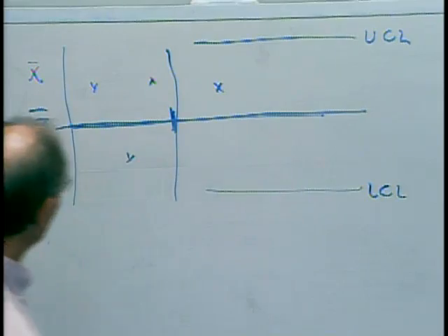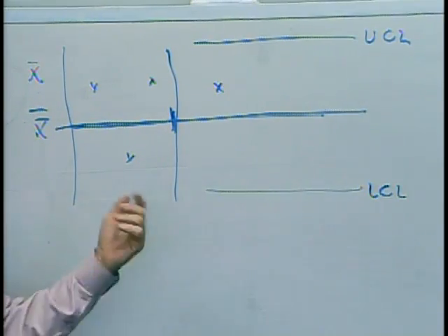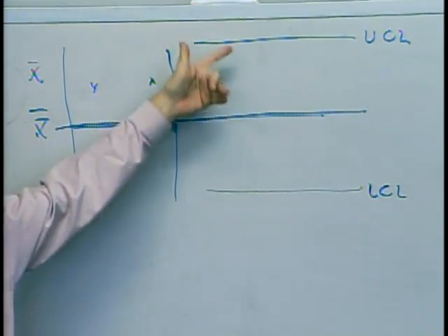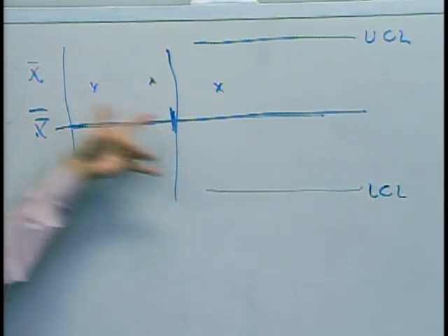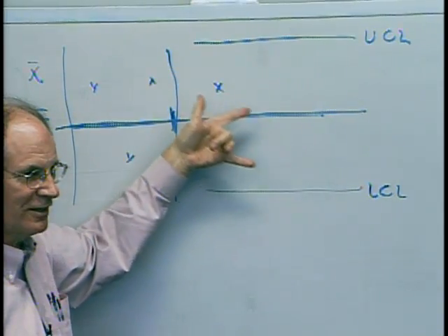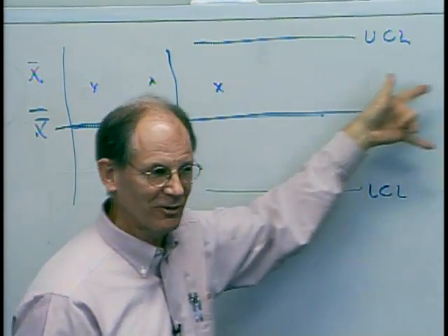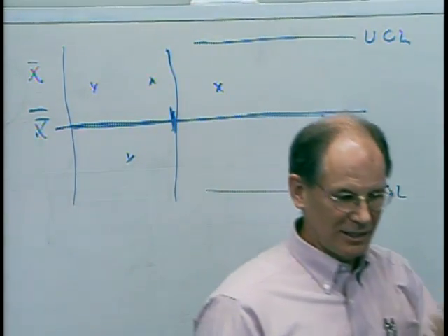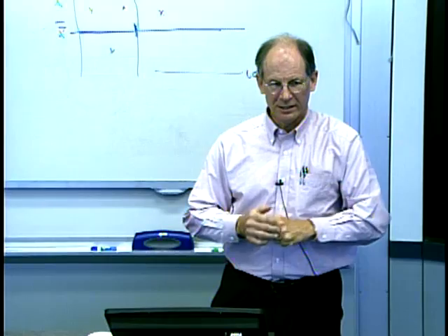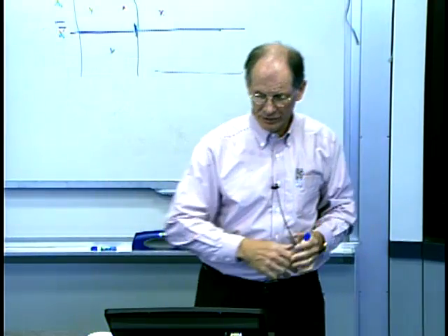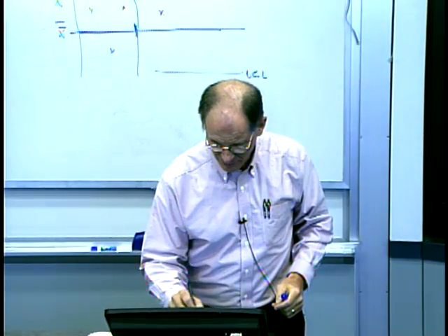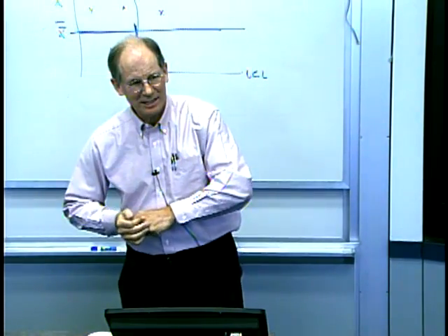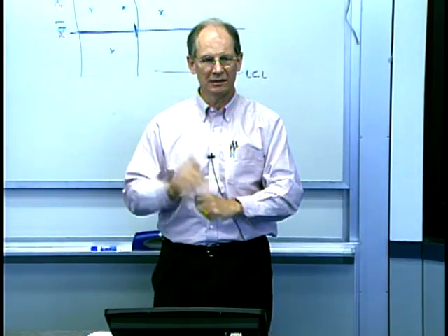And back here it's all over the place, and you just say, oh well, there's the mean value and the standard deviation. You can see that these will be totally bogus limits. And if it's out of control back here and you put those limits on here, guess what? It'll appear to be in control here too. It'll stay within these limits. So it's a bit of a catch-22. But what do you do with these? How would I take these, I don't know, 25 to 50 points before I actually start doing control, and say, okay, looks good?